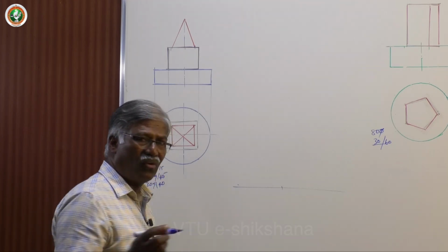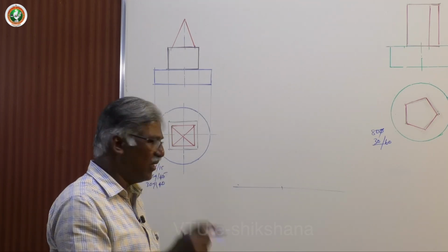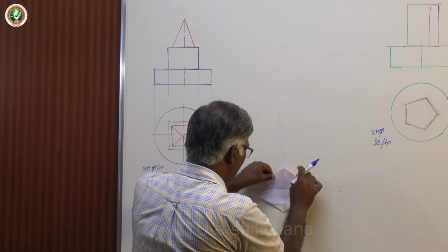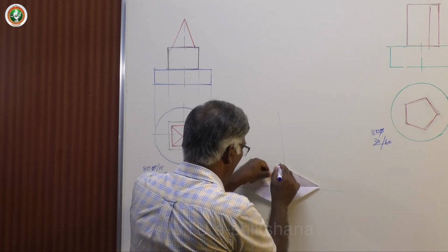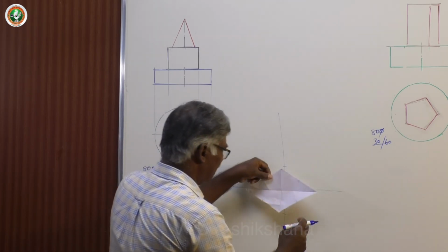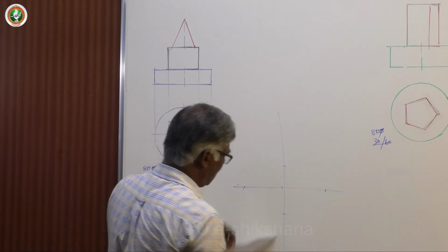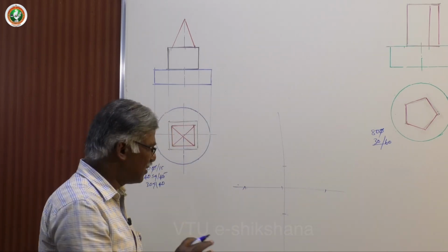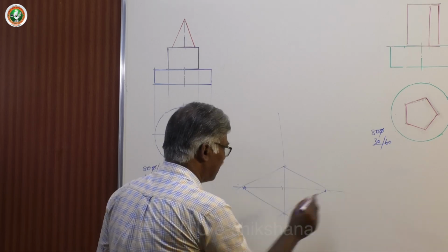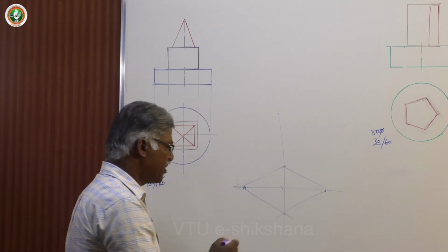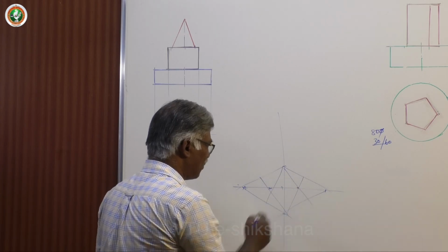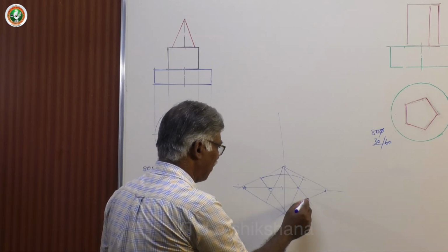So you know, the best method to draw manually is the plus mark. Take the half of the side and mark both sides. Take total and mark here. That's what you have to do. That's all. Within no time you get this ready. Now draw this one, four centers method. These points should coincide. Then draw the ellipse.